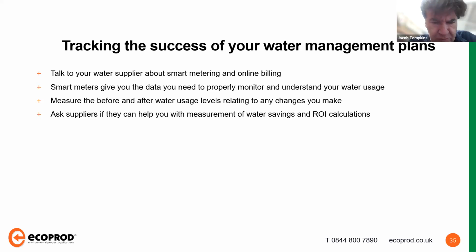Measure before and after any changes you make. So, you know, if you're going to change some urinals, do a couple of measurements beforehand and then do measurements afterwards to see what the actual savings are. And then you can do a return on investment calculation for how much it costs. And ask suppliers whether they can help you.